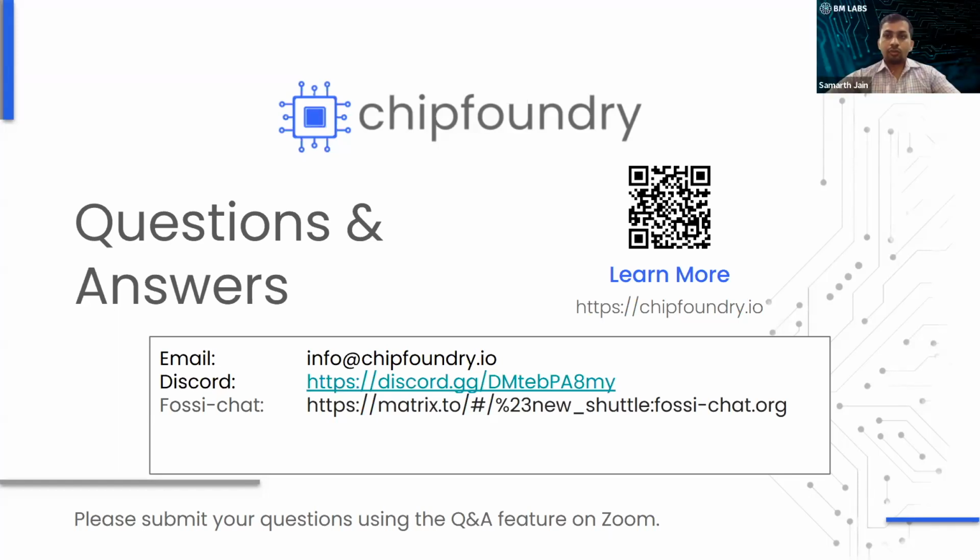So when you do the write operation, as you correctly mentioned, there is the row address, column address, and the analog weight you want to program, that is the data, which was EF in our example, right? So once you program it, you send it to our macro FIFO, it programs it, and then there's one more FIFO which you can send the address and read it back. It's a first in, first out, right? So you can know which address is coming out when you read it.